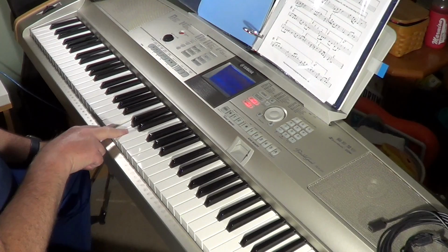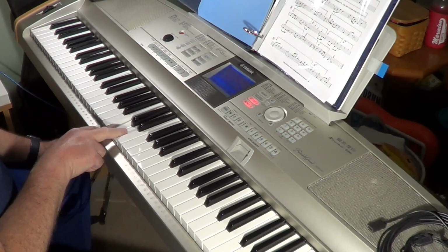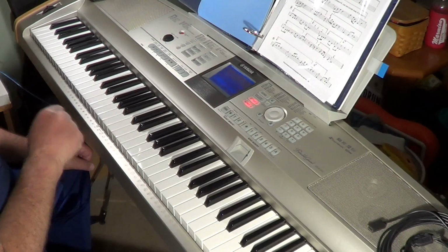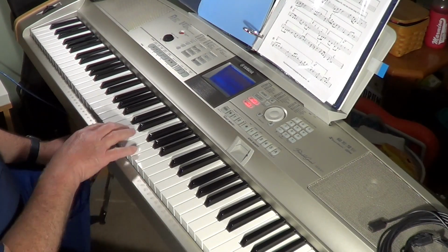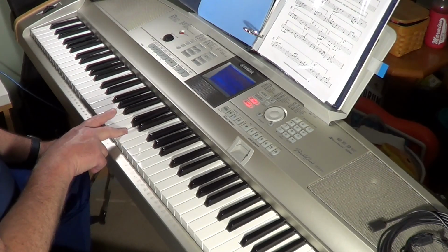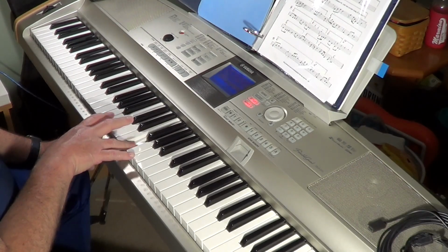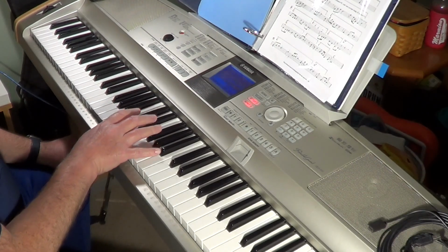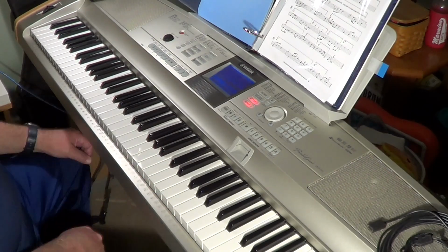Yeah, you see, when I hit the second key, I hear its note instead of the one with the lower pitch. The keyboard should have a priority on the lower pitches, not on the highest. And there is also a problem with the gate signal. Can you hear that? Although I'm hitting all the keys, if I go too fast we cannot hear all the notes, and that's because the gate signal is removed when certain sequences of keys are played.